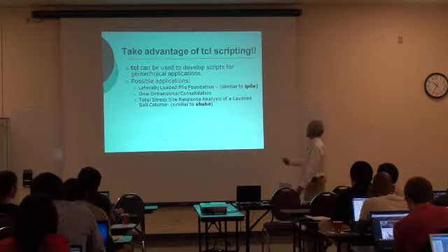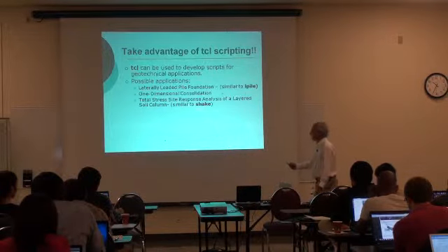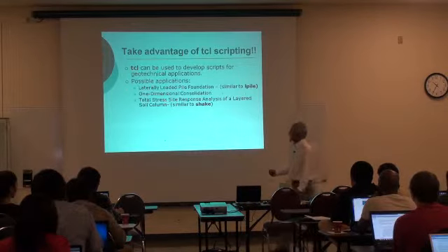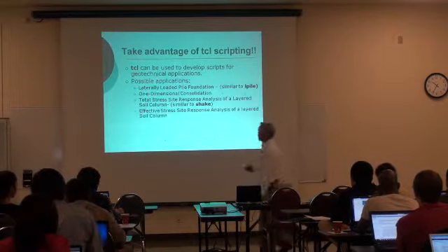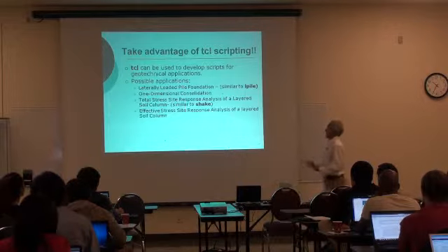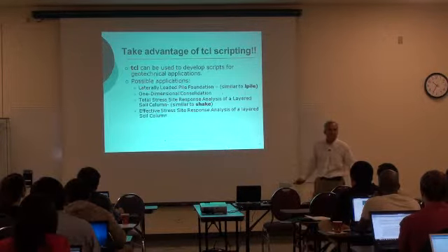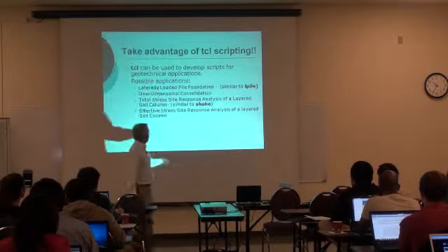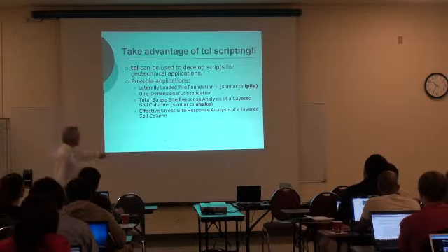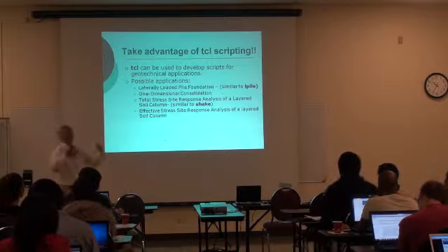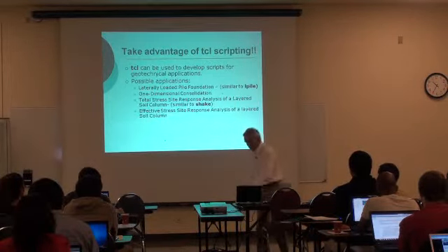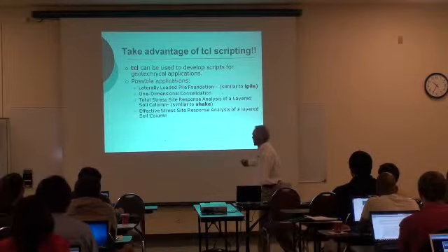Total stress site response analysis. This is what Shake does. So can we do that using OpenSees? Then you can go into effective stress site response analysis, and now Shake cannot do that. So then it's very convenient to have something like OpenSees that allows you to do effective stress site response analysis of layered media. And again, there are some other codes available, but now you are reducing the number of codes that can do this.